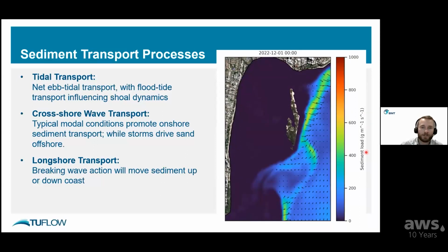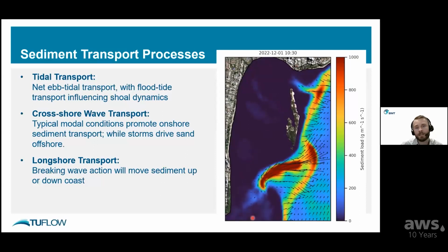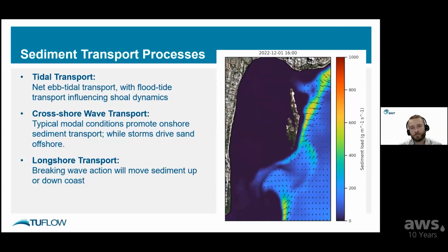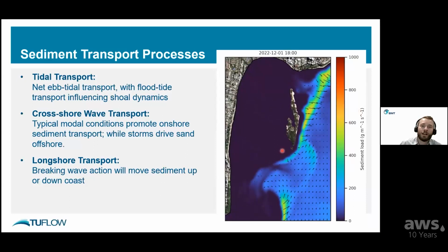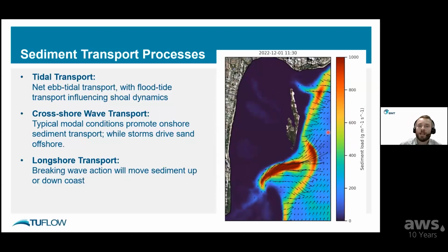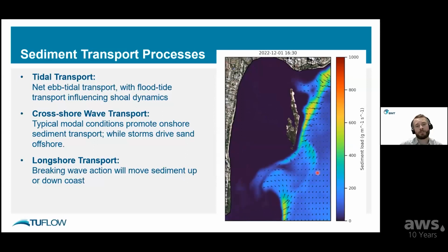Other nice things to notice are the ebb currents. You can see right now that the ebbing transport rate really picks up on the tide, and you can see it also across the ebb shoal out the front. Because we've got quite large waves in this short animation, there is an outgoing direction of sediment, so the sediment is being driven away from the coastline. And of course, there's also the flood current. During the flooding tide, sediment transport does head inwards.